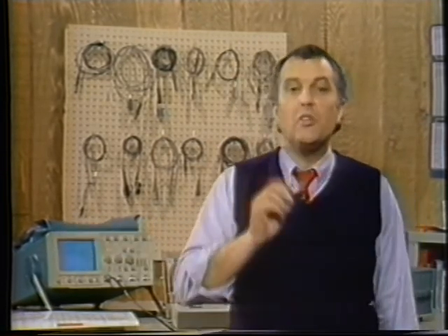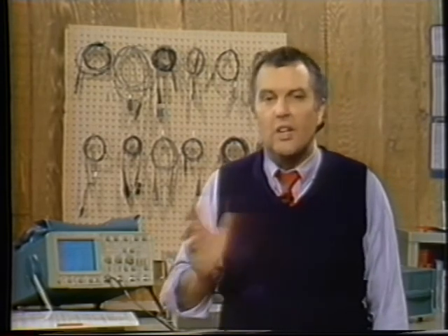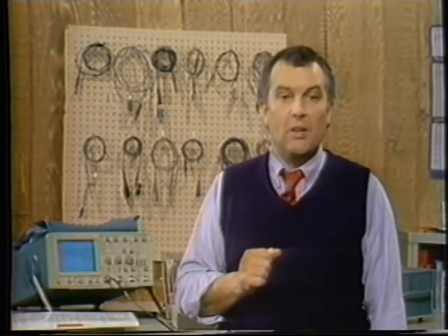If you match them to the probe specifications, you'll select a probe that will enhance the capabilities of the system and not degrade it. Most people look at bandwidth and rise time and just stop there, but that's only part of the equation. As we've seen, there are many different kinds of probes, each with some feature or specification that makes it the best possible choice for some particular application. Consider their specifications in light of your application.